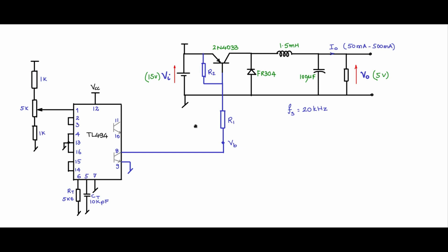But our focus here was to just demonstrate to you how the base drive works. This is a simple base drive, a 2 resistance base drive and a PNP. If you use ground side switching, you can use an NPN transistor and a 2 resistor base drive. However, as you start going higher in power, you will need more complex base drives, and that's what we will look at further.